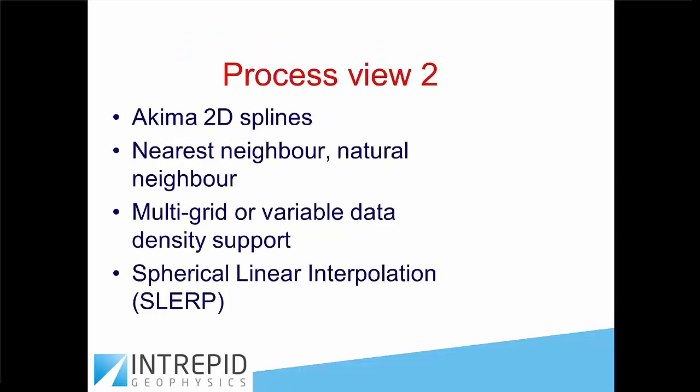When we come to start to interpolate the data, we allow the option of 2D splines, 2D once in the east direction, say, or once in the north direction, or if you're producing a rotated grid, along the rows and then across the columns. That's the first primary tool that honours curvature while interpolating the data.